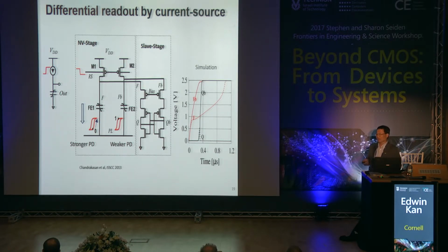And you can see that this is the dynamics. The window has a best place to be sensed. So how your latch is going to take that current difference, there's a best time to take it. If, because of device mismatch, you take it in another place, you just have a smaller window to deal with.